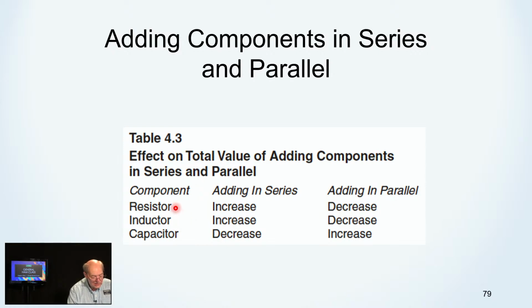If you put a battery across a resistor, there will be some current flow. If you put a battery across a capacitor, just after you connect it, there will be no current flow. So a capacitor is different. Resistor and inductor both conduct. Capacitor will block DC. That's the oddball. It's the one that's different. And notice what happens here with a capacitor.